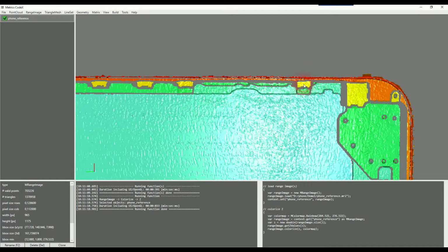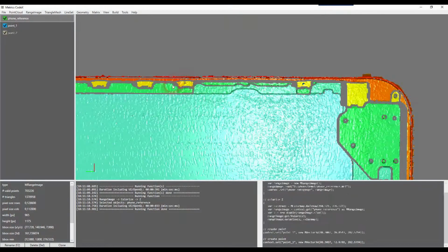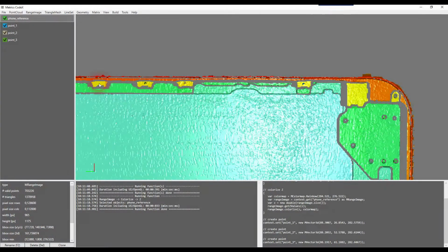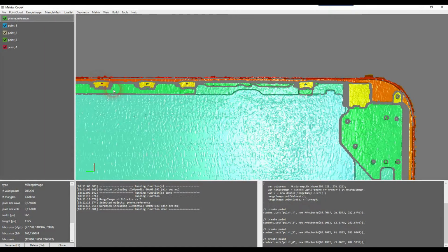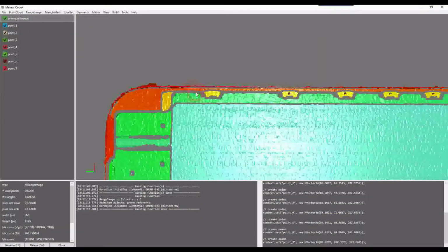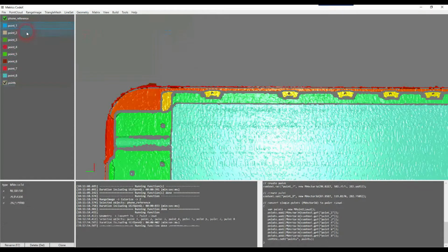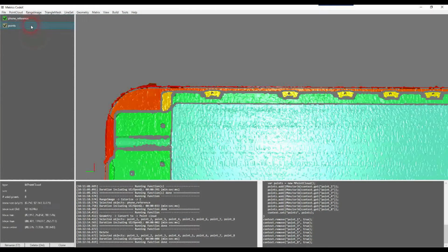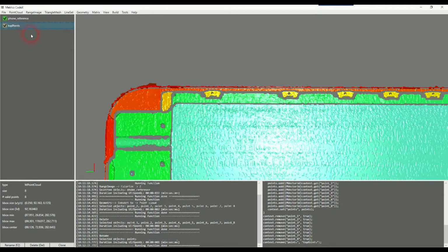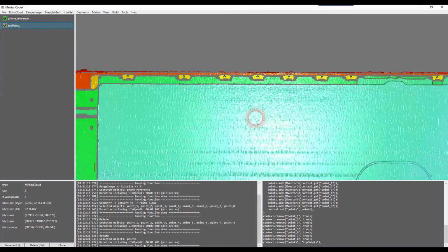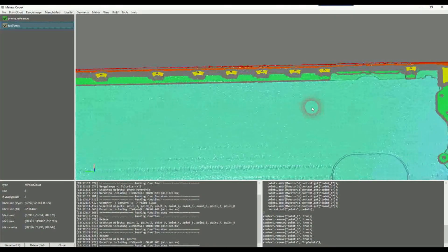here. So I'm just using interactive point picking on this. When you have a CAD model or when you have some values from your customers, some positions, you can use those. But for now, for our purpose here, it's sufficient to use those picked points. Now that those points have been created, I'm just converting those single points to a point cloud, and I'm renaming this point cloud to top points. So this is it for the reference object.